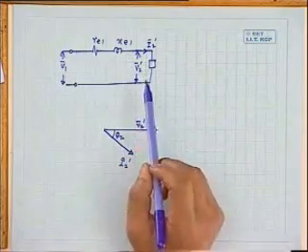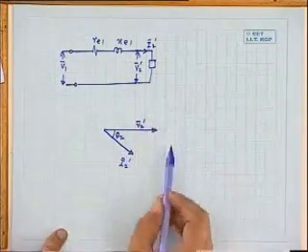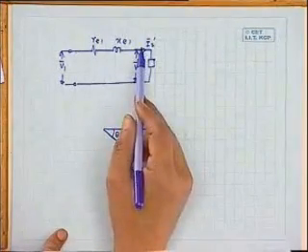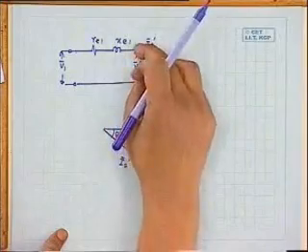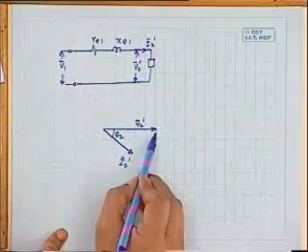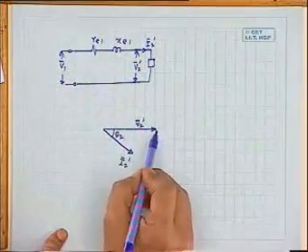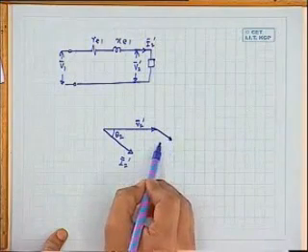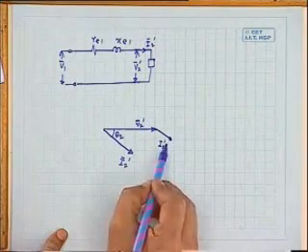Then when this switch is opened, what will be this voltage? It will be V1 only. Suppose you imagine this circuit is opened, so this voltage will be the same as this voltage because no current is flowing. But anyway, now let me get V1 from this phasor diagram.